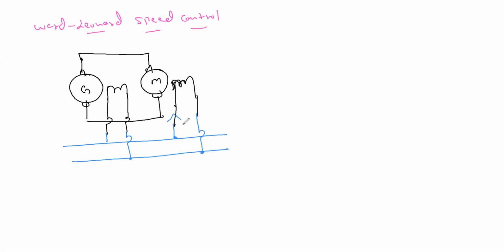So this is the field current of motor IFM, field current of generator, armature current of generator. You are getting armature current of motor. Motor के लिए input generator से आ रही है, ठीक है. And for the generator, what is the input here now? Generator कैसे rotate होगा? Generator rotate होगा जब आप इसको prime mover से connect करेंगे. And what is the prime mover here now? Induction motor. This is an induction motor. And for the induction motor, we require a 3-phase supply.